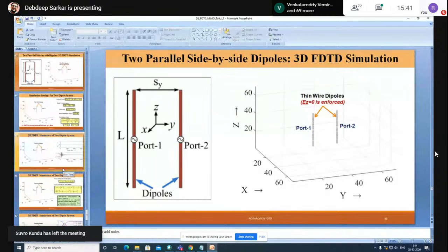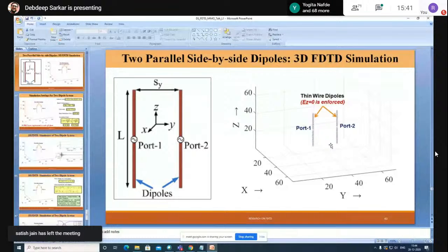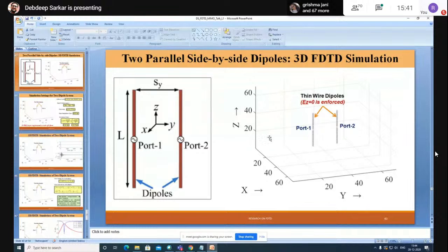But from a physical point of view, what I can tell you is, when you encompass your entire problem space with PMLs, there could be a provision to have a different reflection coefficient. I think 0.001 means very small, so little reflection will be enforced from the layers. I don't know about 4 faces, but in our case, when we model this 3D thing, say a rectangular parallelepiped, we have 6 faces, or for a cube also you have the 6 faces.